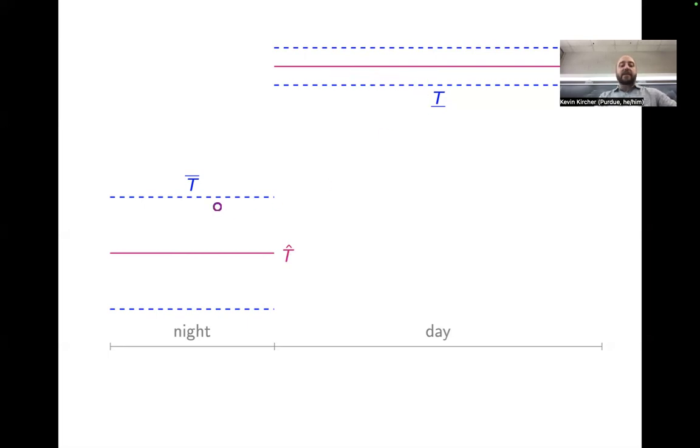And then we imagine that there's a band of allowable temperatures. So during the day, this might be, say, plus or minus 1 degree Fahrenheit. You might say, yeah, people want 72, but is anyone going to notice if it's 71 or 73? Probably not. So anywhere in there, if the temperature is in there, it's fine. And then that band might be bigger overnight, potentially. If nobody's in the building, it probably doesn't matter if you let the temperature swing by 2 or 3 degrees. You don't want it to get too cold, so pipes freeze or something like that, but otherwise you might have more flexibility.